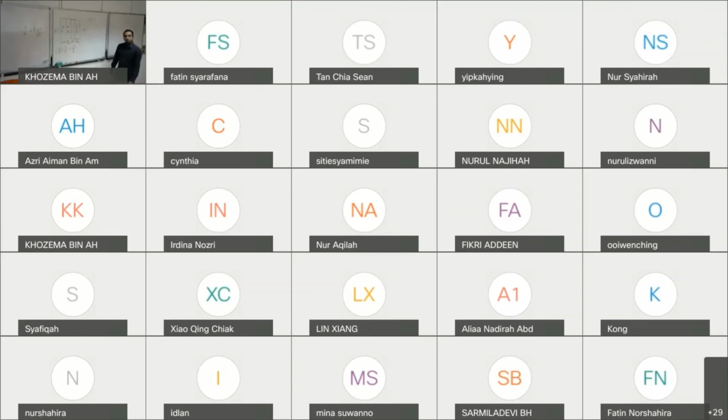You already know the highest temperature minus the lowest temperature. So 18 minus -2, you get 20 degrees Celsius. Okay. Now you have to find the value of R overall. So R overall is equal to RA plus RB plus RC plus RD.